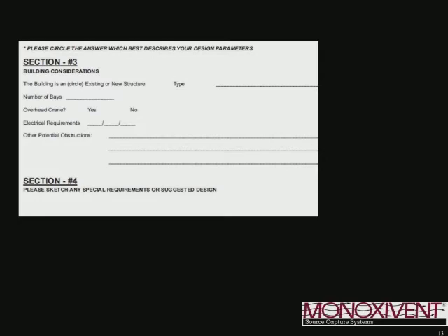First off, when you're talking about the CFM calculations on that spreadsheet a couple slides ago, are you looking at exhaust temperature, or are you using standard air temperature when you're calculating those CFM? Exhaust temperature. Okay. And another question, the required CFMs that we're showing, are we just putting the CFM that's coming out of the exhaust pipe, or are our systems pulling in more air than is actually coming out? Well, we like to size it with 15 to 20% of ambient air, and that just helps make sure there's no leakage around the tailpipe, but it also helps cool the exhaust as it goes through the equipment.